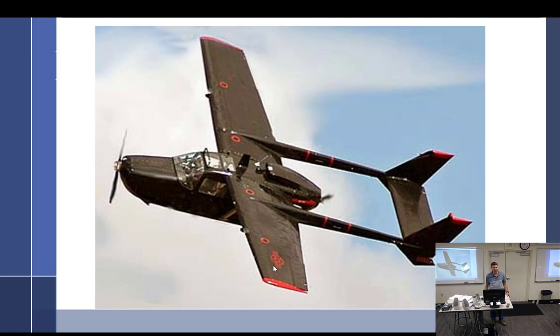So the airworthiness directive is, in this one, you don't grab both throttles and go up. You grab the rear engine. You bring the rear engine up. You get forward momentum thrust off the rear. When you have positive thrust, then you bring up the front one, and then you take off and go. So that was an AD and a change to the POH.